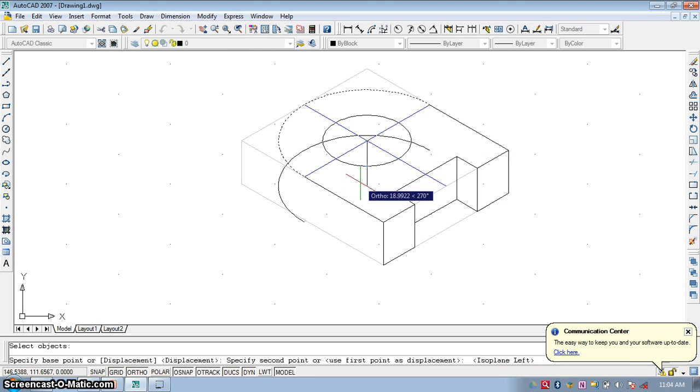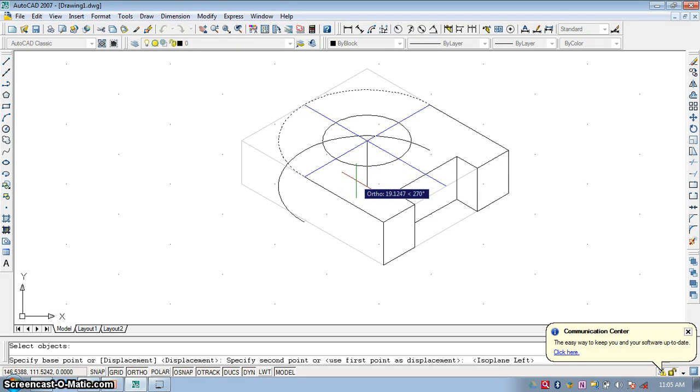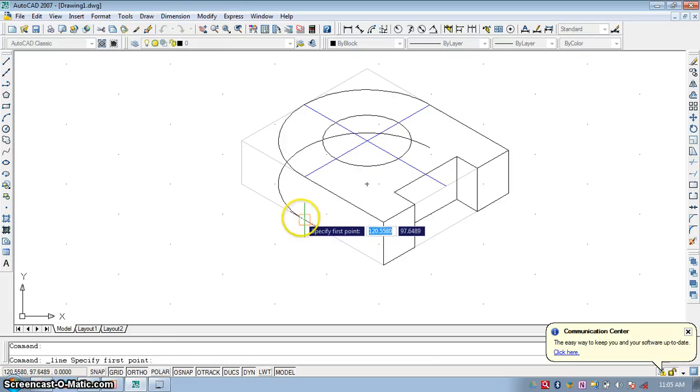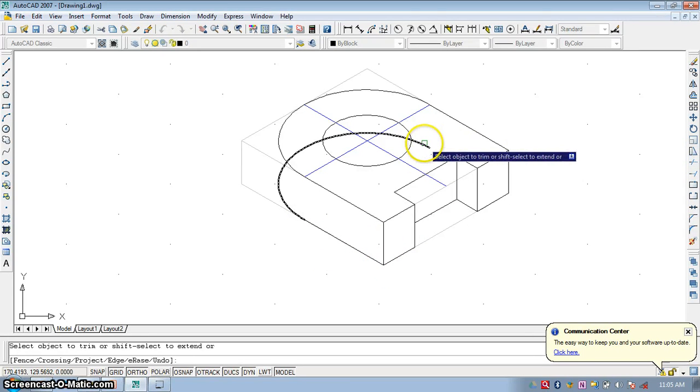Every cursor, if you change the mode, has a different mode of freedom. So I want to move it in a downward direction, so according to that, distance is equal to 18. So enter here 18, so it would be moved. Okay, and then I will just join this point to this point, and whatever the overlapping part, I will remove by the trim button.